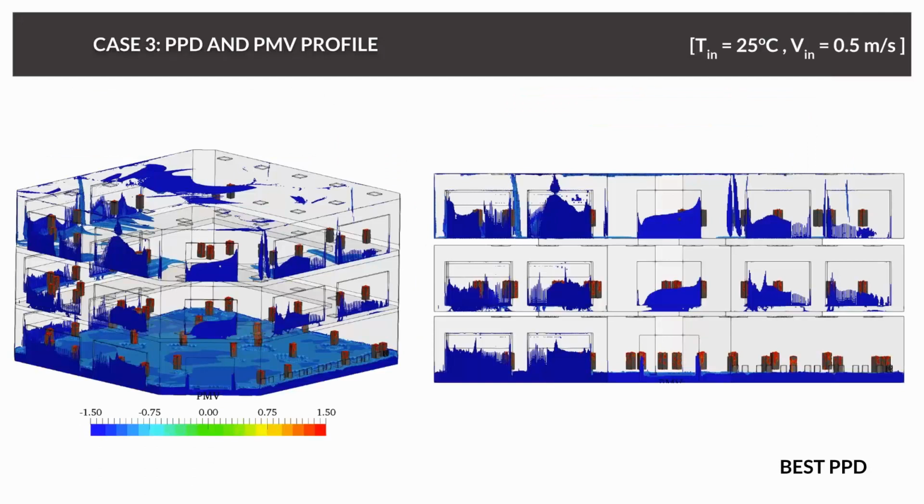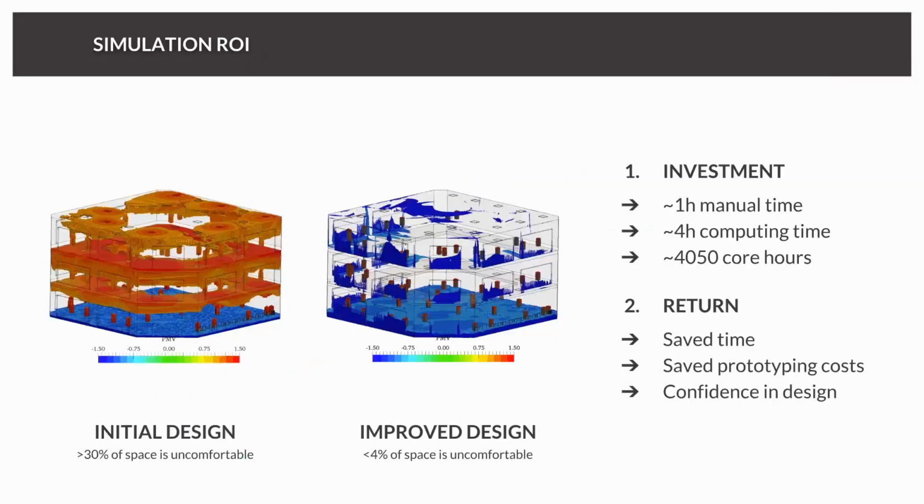Yes, and this is a PPD representation and PMV profile for case number 3. And now it's completely different. There is just a small area where PPD is higher than 10%, and everywhere else the conditions are really perfect.